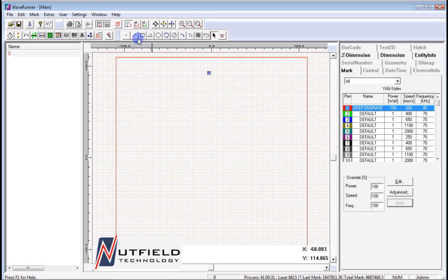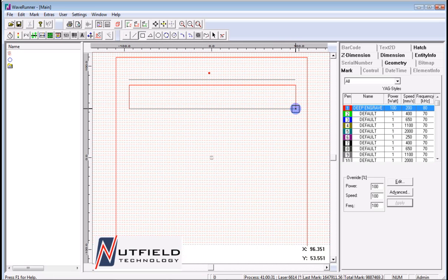For the point, the single click is all that is required to generate it. The line uses the first click as the start location of the line and a secondary left click to position the end of the line. The Rectangle tool is slightly different in that the operation is left click and hold at the point of the first corner, then drag and release to generate the opposite corner.